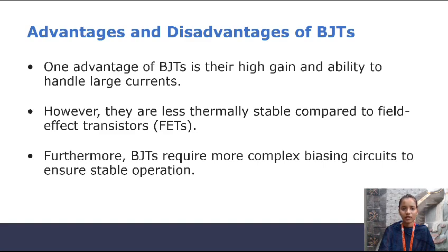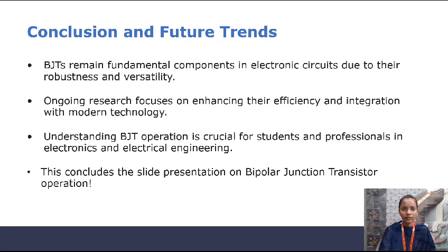Advantages and disadvantages of BJTs. One advantage of BJTs is their higher gain and ability to handle large currents. However, they are less thermally stable compared to field effect transistors (FETs). Furthermore, BJTs require more complex biasing circuits to ensure stable operation.